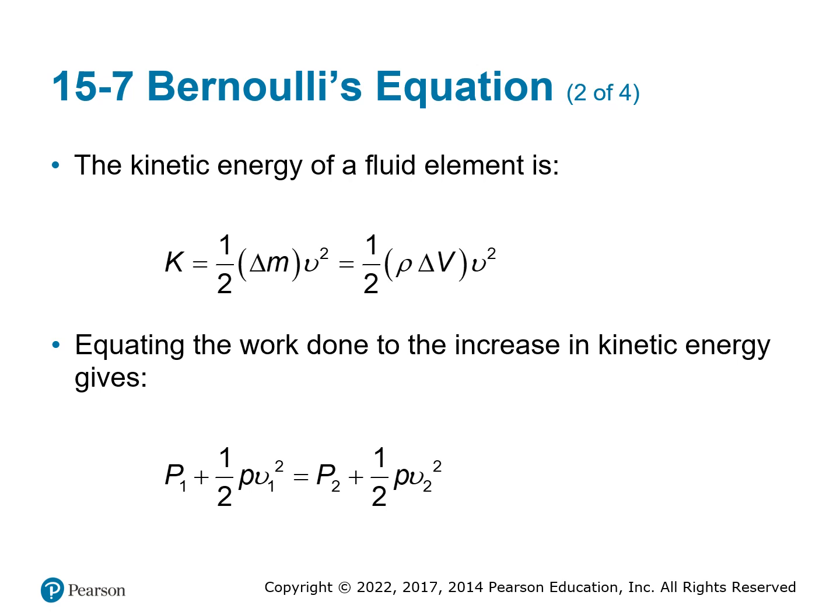Bernoulli's equation. So Bernoulli's equation takes fluids and energy and kind of puts them all together. So you can calculate the kinetic energy of a fluid, right? Because if it's moving, it has kinetic energy. So 1/2 times the change in mass times velocity squared. You can rewrite that as 1/2 times the density times change in volume times velocity squared.